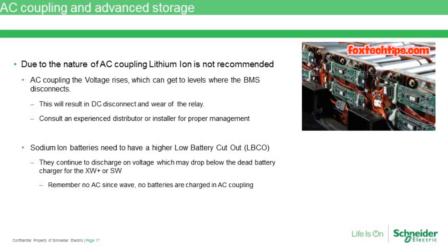So here's something that's definitely worth considering when we're sizing out a grid tie with battery backup system. The customer's chosen something that is going to be normally selling power back to the grid. So when speaking with the customer, how often they're losing power may be a really important question at the end of the day, simply because most of the time when we're sizing out batteries, we size for 50% depth of discharge, or if it's self-consumption, it may be 25% depth of discharge. But the thing to note with grid tie with battery backup is they're going to be connected to the grid 99.5, 99.6, maybe even higher percentage. Their power outages could just be once or twice a year.